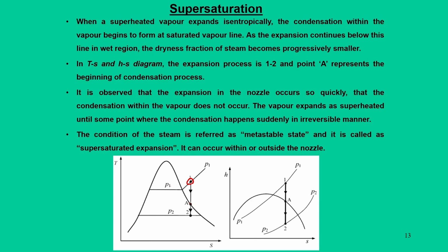But unfortunately, since the dynamics of this change is so fast, the fluid does not condense instantly. It has to take some finite time, and after that finite time the condensation starts. So, instantly the condensation does not happen. The condition of the steam at that particular state we call a metastable state, and the expansion is known as supersaturated expansion, and it can occur within the nozzle or outside the nozzles.